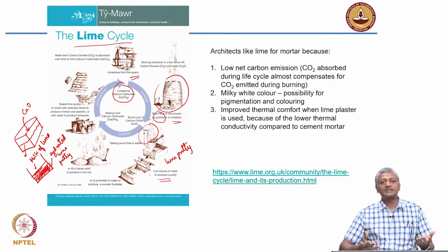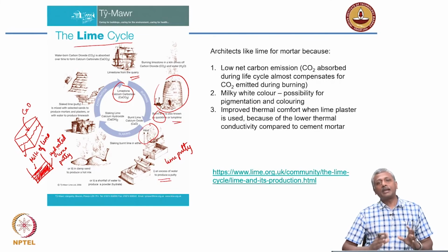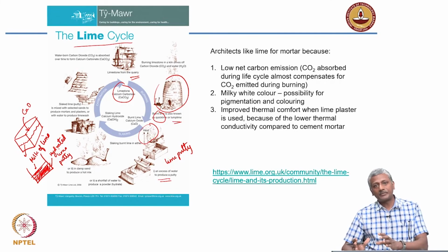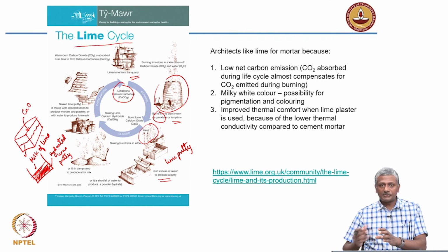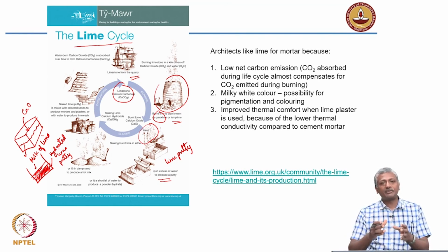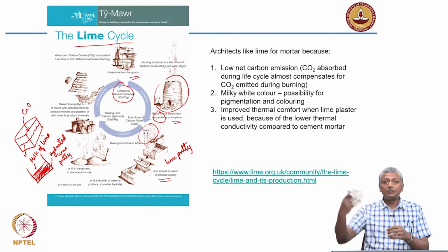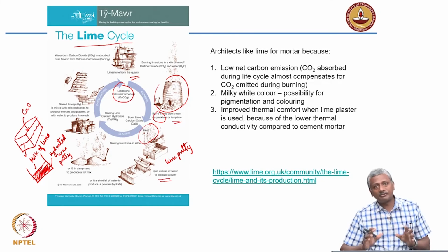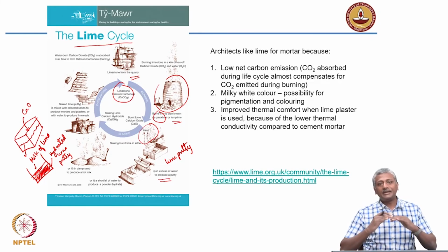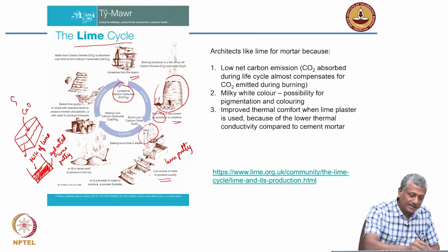The process of slaking simply is done so that all the lime gets converted to hydrated lime before the use in mortar. This is very important because the process of slaking ensures that you won't have any remnant calcium oxide left out, which will convert to calcium hydroxide later in the structure. So that's very dangerous. You want all of it to get converted to hydrated lime in the slaking tank itself. So that's called a slaking tank.